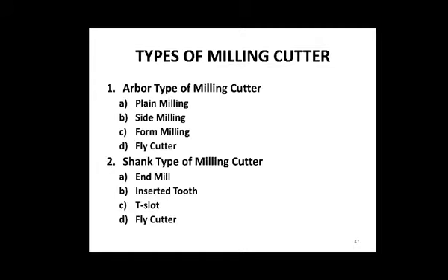There are four critical angles of each cutting tool: end cutting edge angle, axial relief angle, radial relief angle, and radial rake angle. Depending on the material being milled and what task should be performed, different tool types and geometry may be used. For instance, when milling a material like aluminum, it may be advantageous to use a tool with very deep polished flutes and a very sharp cutting edge.